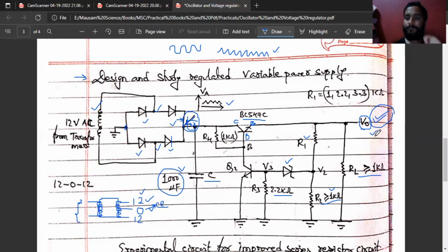There will be a minimum amount of ripple, so that we cannot directly convert all the AC into DC. Some small part of AC can be seen at such a terminal. If we go to millivolt here, then a little amount, like 0.006 or 0.004, can be seen. Suppose 0.004 millivolt of AC can be seen over here. And a larger amount of DC can be seen.